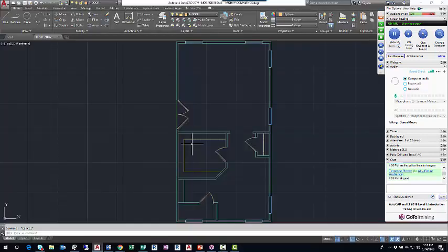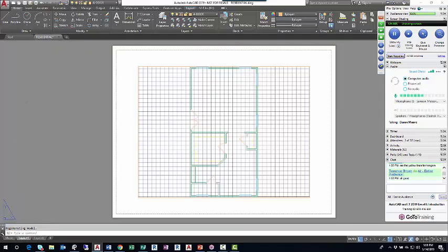So it looks like this. Save the drawing. There's never a bad time to save your drawing. Once the drawing is saved, down in the lower left corner of the drawing window, or below the drawing window even, we have these layout tabs. It doesn't matter which one you click on. I have a habit of working left to right, so I'm going to start with layout 1. Okay, so here's layout 1, layout space, paper space.